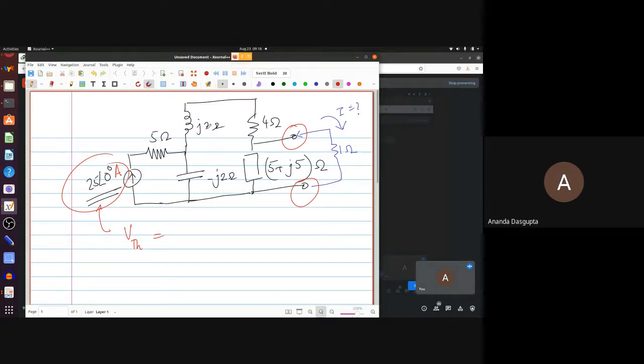But the important point is you know that this is a current source which is driving 25 amperes in here. And now these are two parallel branches. This is one parallel branch. This is the other parallel branch. Remember, you have disconnected the 1 ohm, so there is no current flowing out through this. So this whole thing is one series combination, and these two are in parallel.